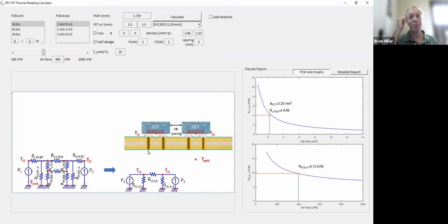If you're up for each little bit, then you have to have the trade-off of the board house. Is it what you want? Is it stable over temperature? You have to make sure there's no outgassing. Everything else does what you want it to do with a conductive fill in the vias. So we reached the conclusion that because of the board houses, and because of minimal impact, non-conductive fill vias are probably the best.